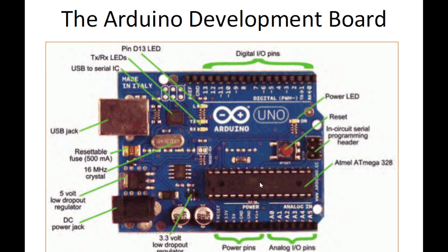DIP or PDIP. Most commonly you will see on the top left there either is going to be a dot on one side or a notch in the center, and that information is there to tell you where pin number 1 is. In this particular case, pin number 1 for this microcontroller is right here. So 1, 2, 3, 4, 5, 6, 7, 8, 9, 10, 11, 12, 13, 14. The 15th pin is here, and all the way to pin 28.